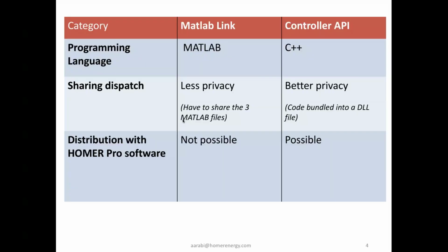Now let's look at the differences between MATLAB Link and controller API. So the main difference is in the programming language you use to write a custom dispatch. If you're using MATLAB Link, then you'll be coding that in MATLAB, and in controller API, you'll be using C++.